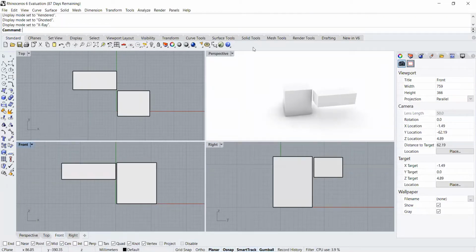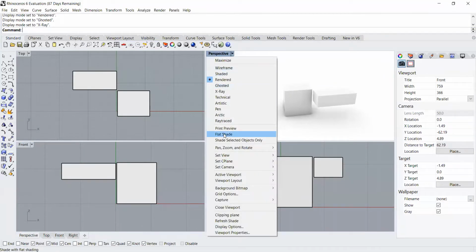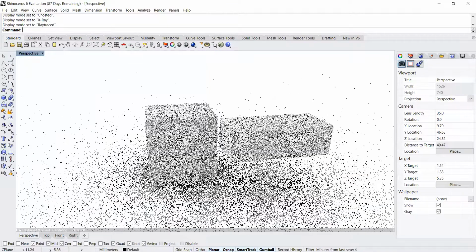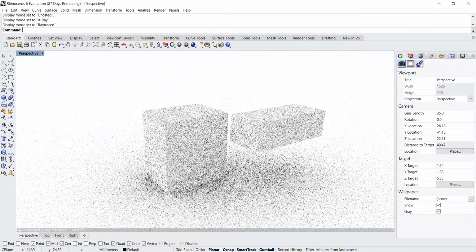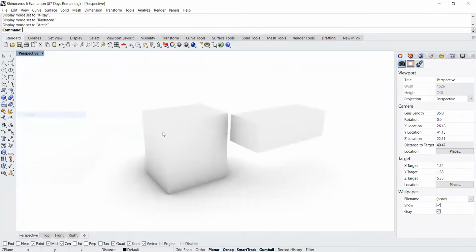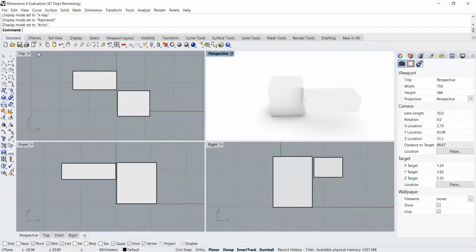These are all the styles. I haven't talked about it last time, but styles are important because while doing complicated models, styles help us. Even for presentation purposes, we can use ray trace. Right now I don't have any material over here, but materials look correct, and also the lights and shadows work here. You can try with styles. So this was about the viewports.